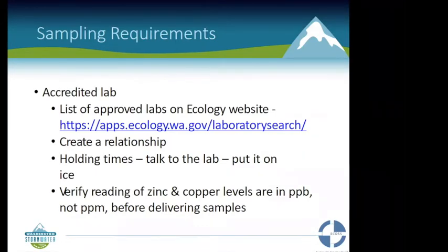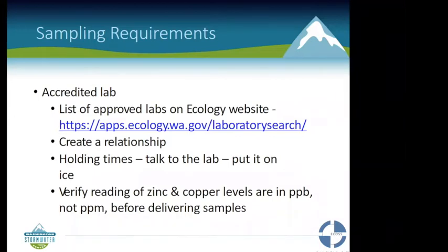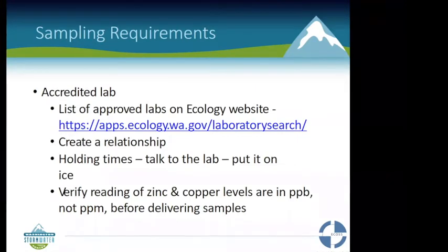The holding times are important because there are certain analytical tests that you have to get your water in by a certain time within a certain window, and you need to verify that you're reading the zinc and copper levels in parts per billion and not parts per million, which is something that you need to talk to your lab about and make sure that they are reporting it to you in that parts per billion so you can read it correctly.